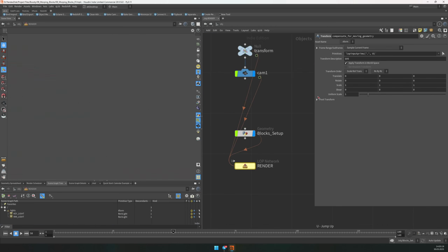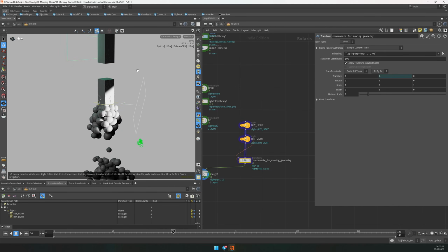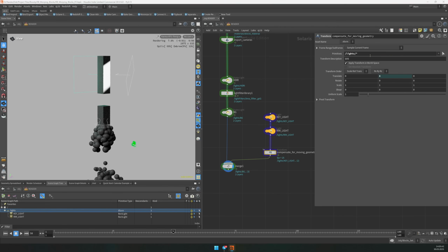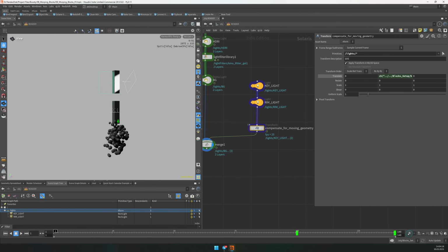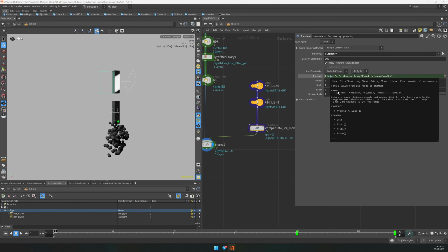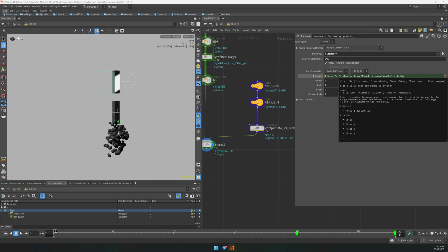So we copied this parameter, and in here we're just going to say paste relative reference. By default our light goes up, and it's also affecting only the rim light, but we want to affect all the lights. So let's take this lights group and put it here, so we change all the lights. The other thing we want to do is reverse these values. We know this value starts from 4 and ends up at 2, but we want to reverse that, so it starts at 2 and ends up at 4.